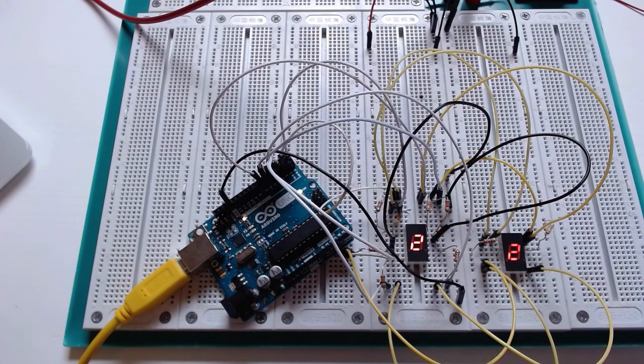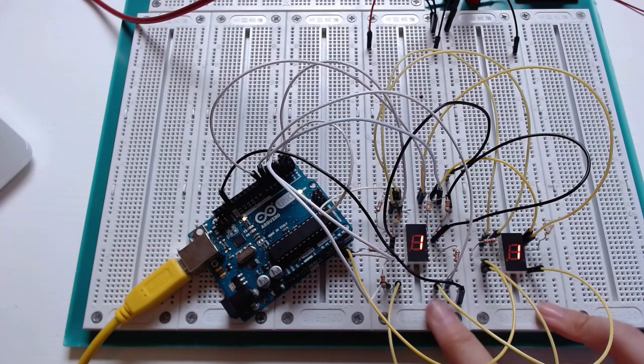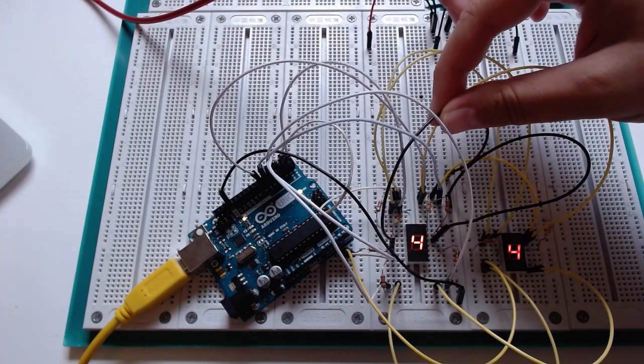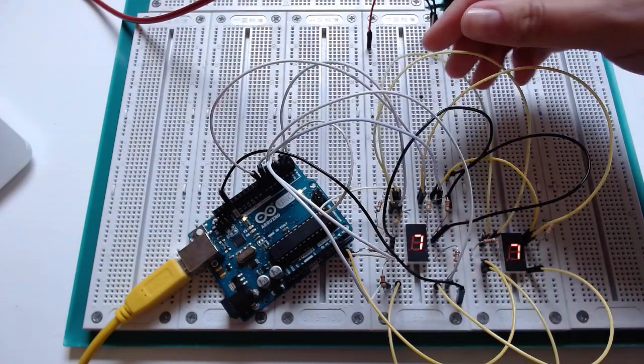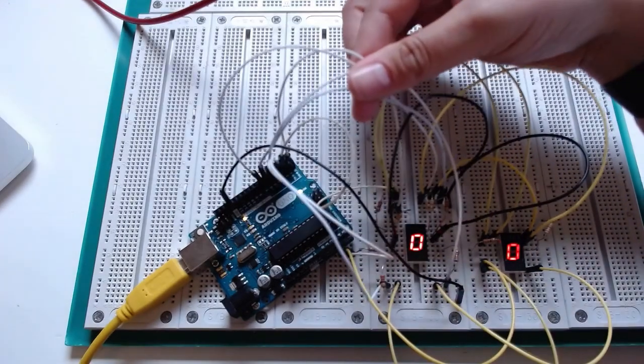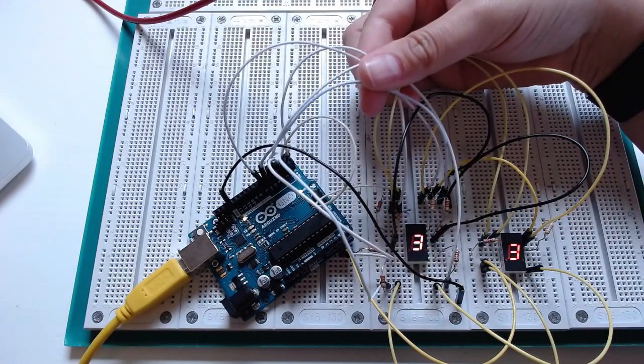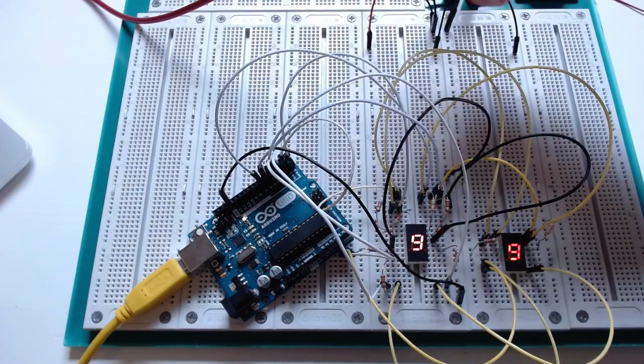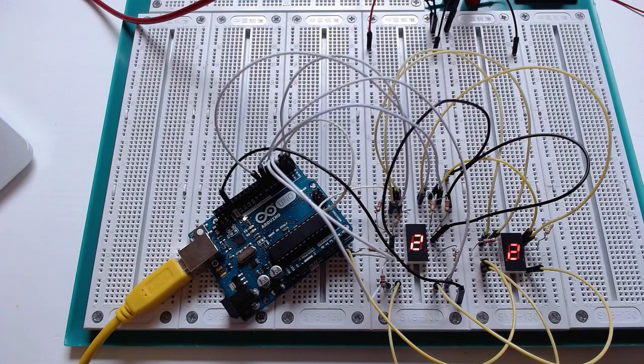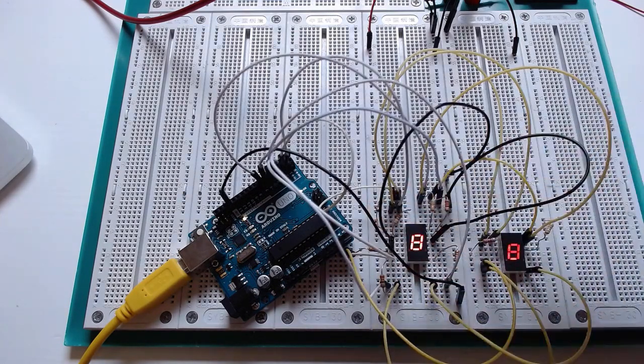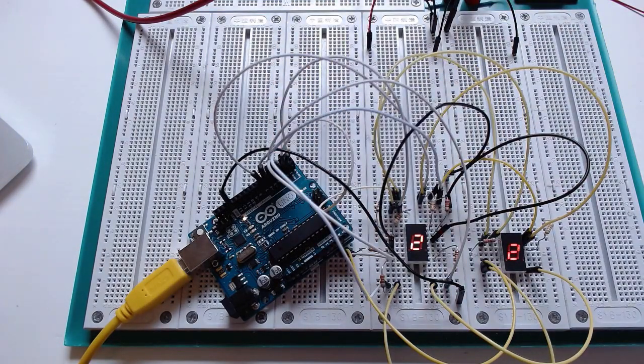I'd also like to point out that none of what I've discussed in this entire video changes if you're talking about a common anode versus a common cathode display. So these are common cathode displays, which means that the common pins go to ground and our segment pins, or anodes, go to power when we want them lit up or ground when we want them turned off. In a common anode display, we're still going to have all of our individual cathodes connected via a resistor to our driver, and we're just going to have the common anodes connected to power.